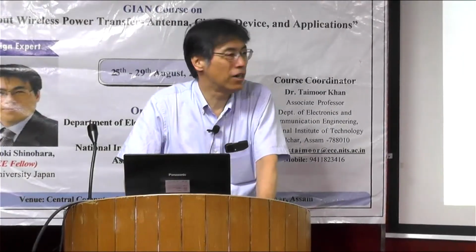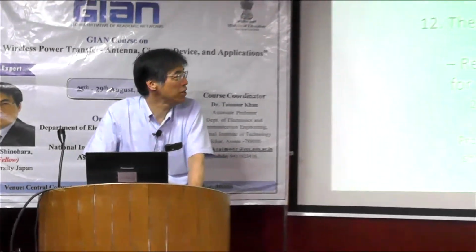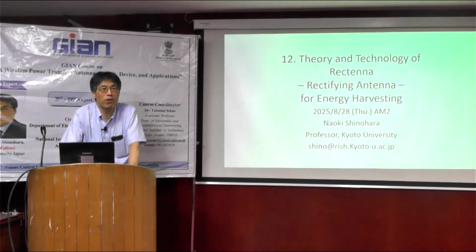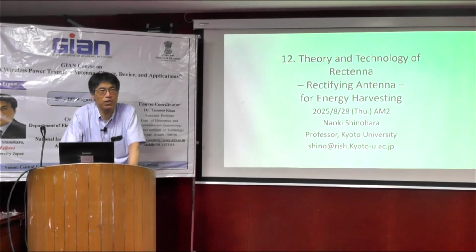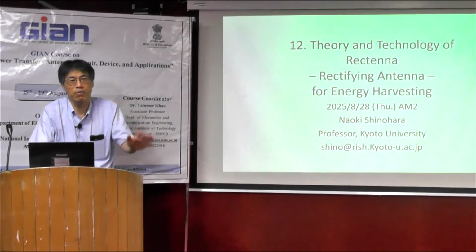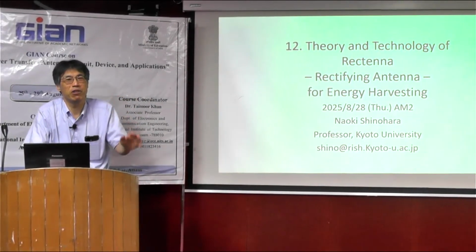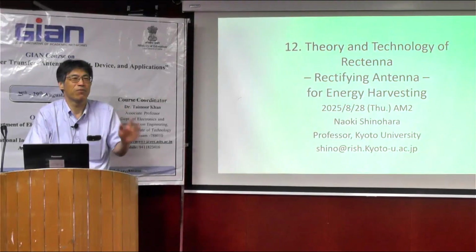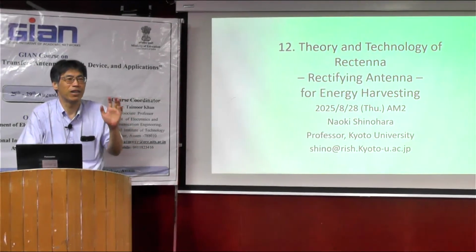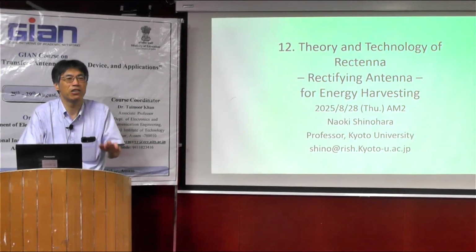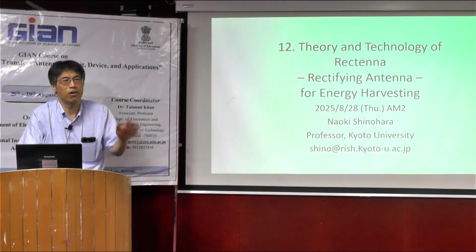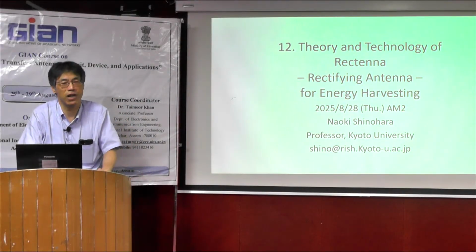So next, I'd like to introduce the same rectenna technology, but I focus on the energy harvester, the low power rectifier. As I mentioned, if we can develop a very excellent rectifier close to, for example, 95% or 100%, if the input power is very weak, like in an energy harvester, efficiency suddenly decreases by the junction effect of the diode.